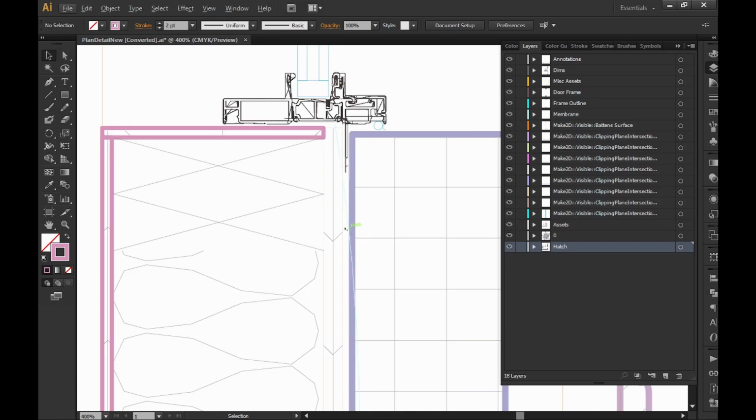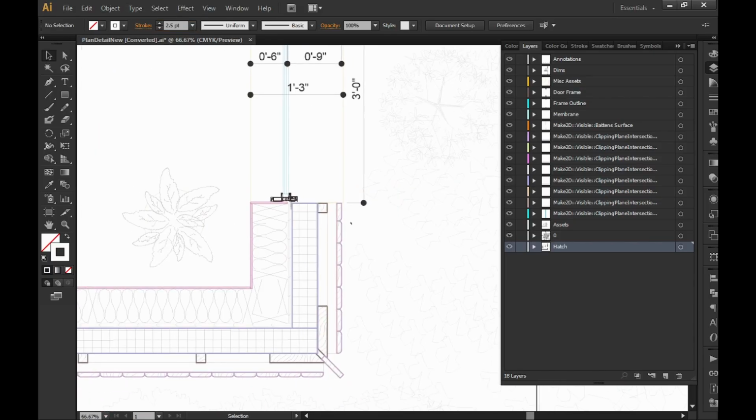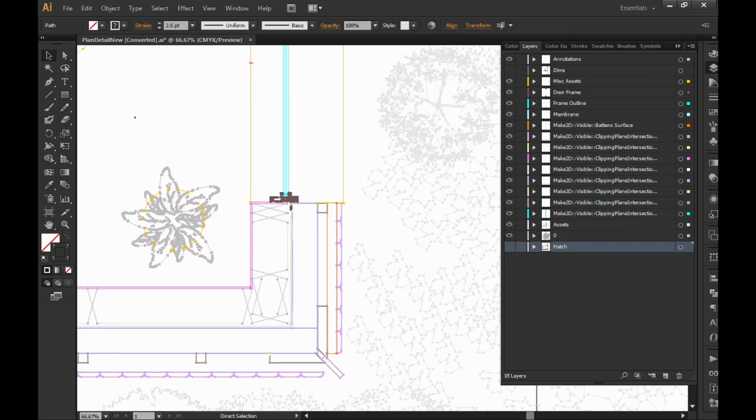And also here the sheathing, right? So I click here again. I'll just find the sheathing over here. I'll probably make that like a 2.5. All right, nice. You can't see it because it's white, but let me go ahead and make everything black. Let me turn off the hatch layer for now. Let me turn off dims and select everything, and let me make everything black.